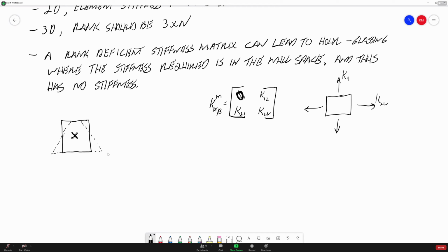A solution could be changing your integration rule or upping your integration rule to a higher order. Excuse me, so you have more integration points. So in this particular case, it would be solved by maybe changing it to a 4-point integration rule rather than a single point integration rule. Okay.